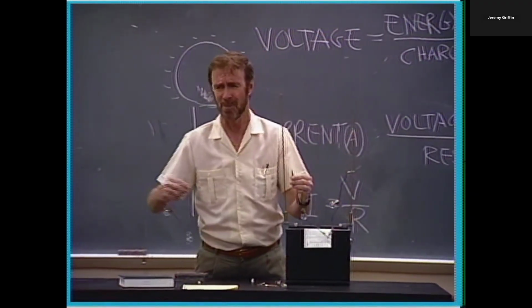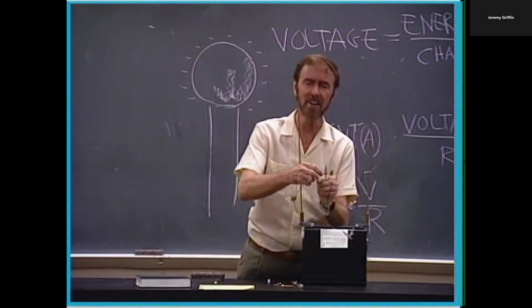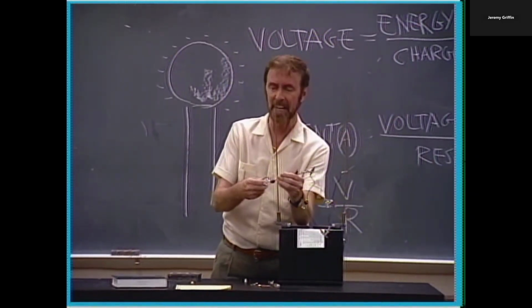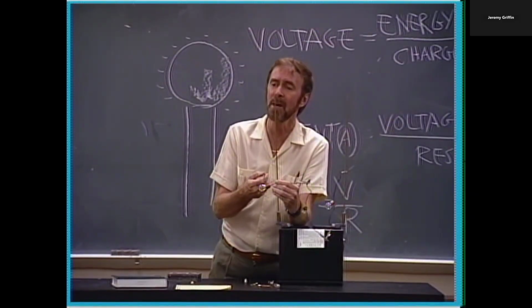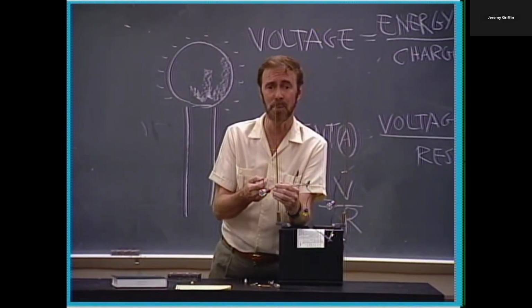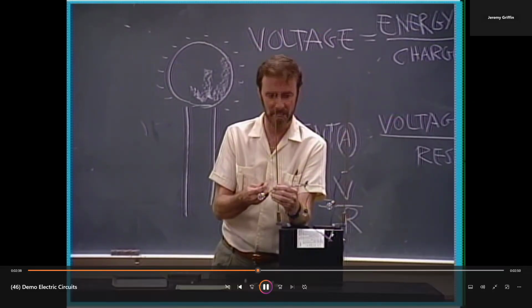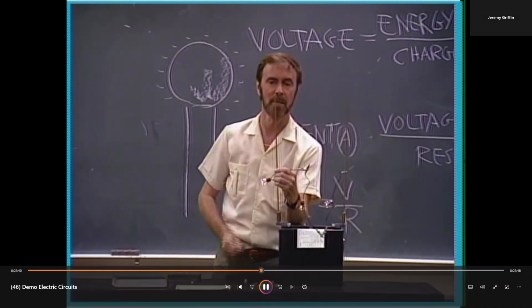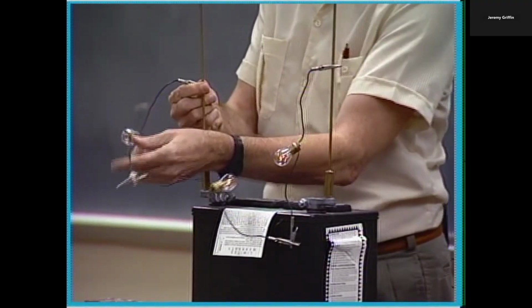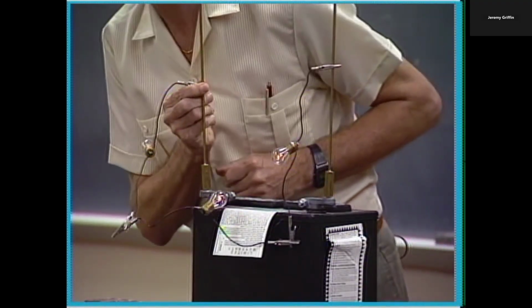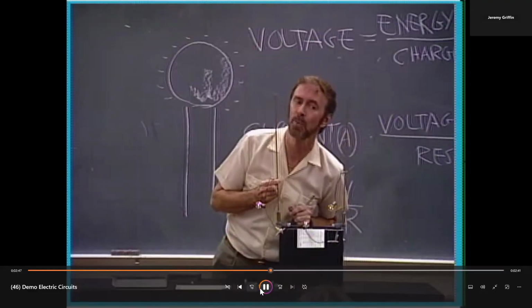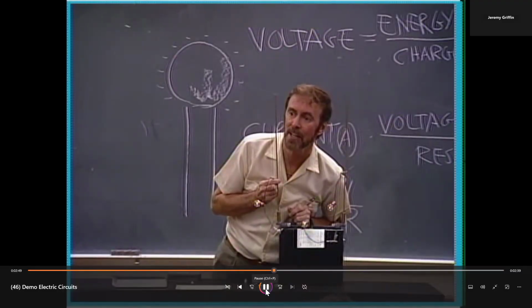All right, now here's what I'm going to do. And everyone's going to get this right. I'm going to hook another lamp in series, and I'm going to connect it up, and you're going to tell me brighter or dimmer. Is there anyone says brighter? No, nobody say brighter. And what do we got? It sure is dimmer. Let me ask you guys a question. What's the voltage across the whole system? 12. Okay. How much resistance we got now compared to before? 3 times. Here, let's do this. Guys, if the whole thing is 12 volts, and you split that into 3, how many volts drop across each individual bulb? Yeah, 4.